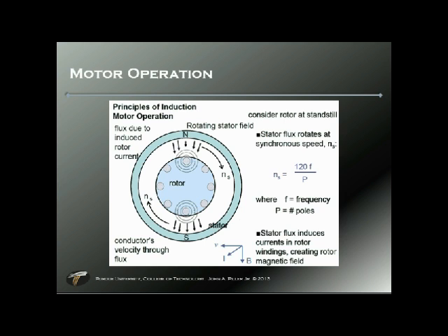Let's roll that up into a motor format. The stator has a rotating field. The field is rising and falling at different locations along the stator, around the circumference of the stator. That is causing a magnetic field to rise and fall in the conductors of the rotor. All those squirrel cage devices of the rotor, the bars across the rotor that run horizontal and then are shorted together on the back end of the rotor, cause a current to flow, much like the secondary of a transformer.